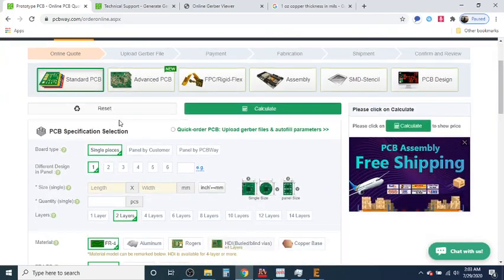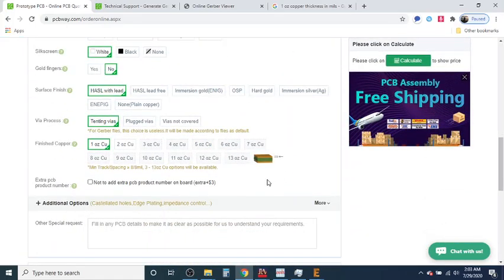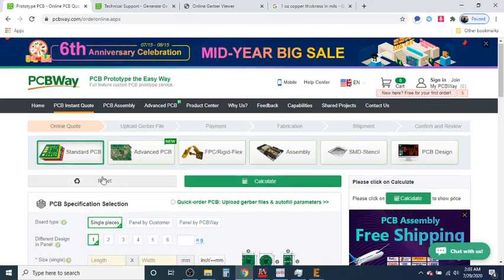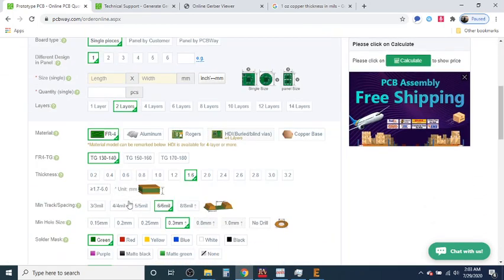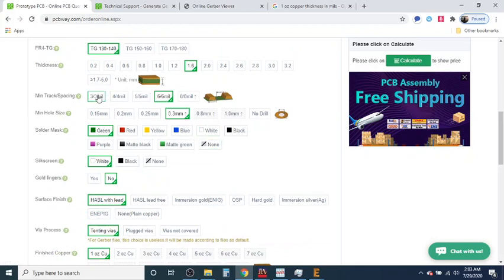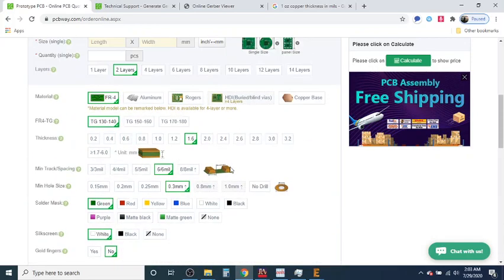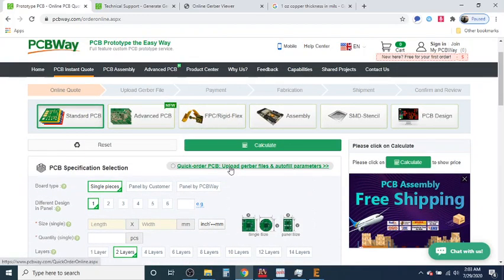So this is a good way to start for designing the PCB. Before you start placing vias, make sure that the spacing is within a certain range, because if it's too small, you're going to be paying more money for something that had a smaller spacing. Probably because it has to have a lot more care to it.